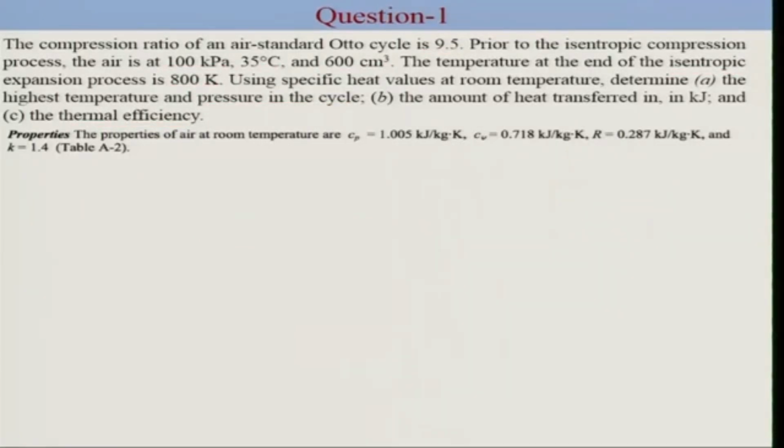So from here we get T2 equals T1 times V1 upon V2 to the power k minus 1.